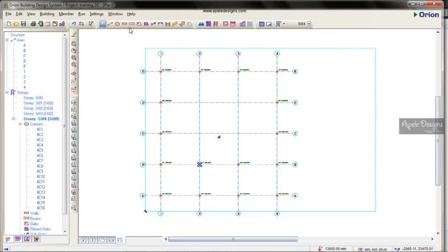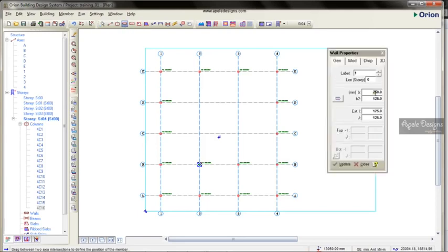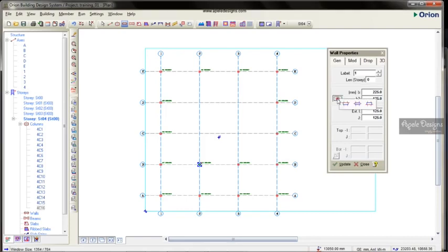And next thing we'll do is create a shear wall. Take shear wall, let's give it a width of 225, and we'll align it to the center, and use the same values for the extension points. I'll draw our shear wall.